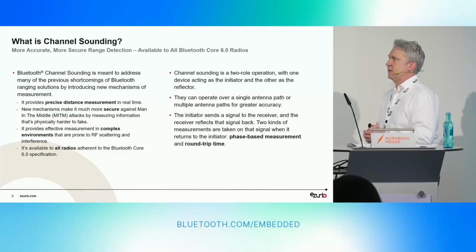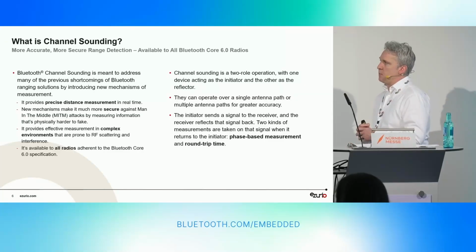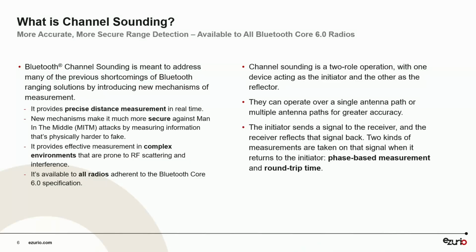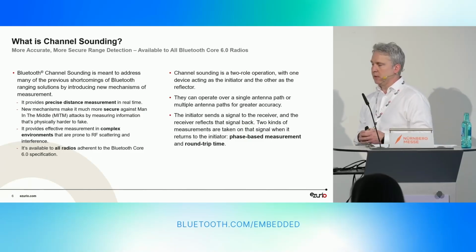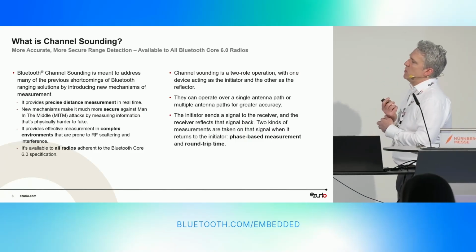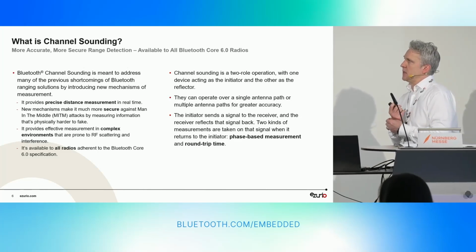Again, a lot more text there for you to take away in your own time, but it's about precise distance measurement. And really, it utilizes a couple of core new mechanisms or concepts we'll talk about right down there at the bottom: phase-based measurement and round-trip time. So you'll hear the acronyms of PBR and RTT throughout this talk. And really, it's the combination of those two that will help get channel sounding to where it needs to be for that precise distance measurement. And we'll talk about these concepts of PBR and RTT in the next couple of slides.